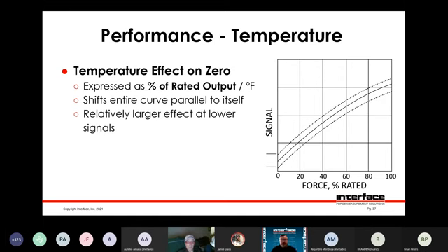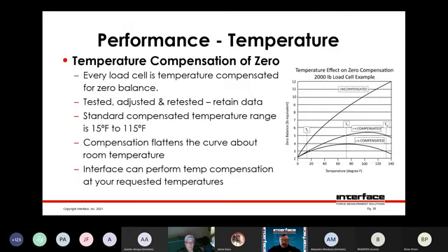This is one that has relatively high impact on load measurements when you're trying to measure in the low part of the load cell's capacity. So even if you have a very tight temperature spec, if you have a large temperature swing and you're measuring, say, at 5% of the load cell capacity, the errors are based on the whole capacity of the load cell. So it's a 1,000-pound load cell based on 1,000 pounds. So these can have significant impact on low-level measurements because they're a big proportion of what you're trying to measure.